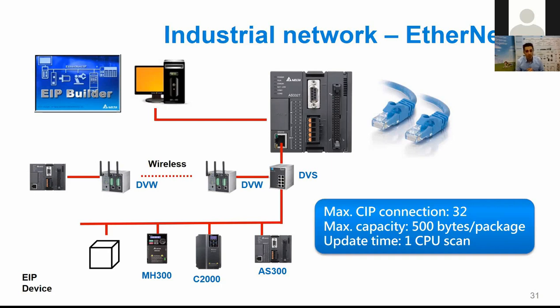Okay, we have a question. Is the power module mandatory for the AS series or optional? Thank you for the question. I forgot to mention. No, it is not mandatory. It is 24 volts only, so you can use your own power supply. But in addition, we also have our own power supply like the AS-PS02, which is simply a power supply. So no, it is not mandatory. You can also supply it with your own 24 volt DC in your cabinet. Thank you for the question.